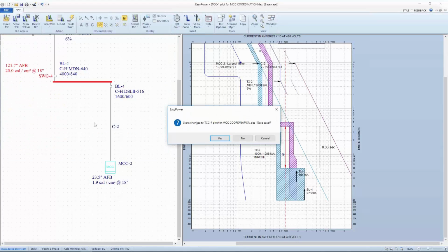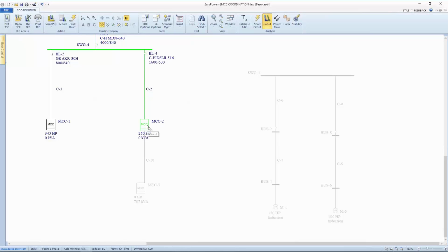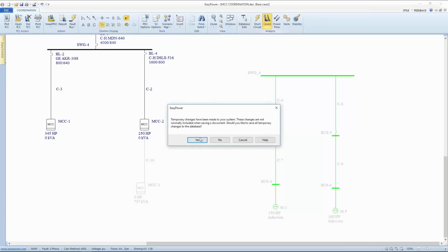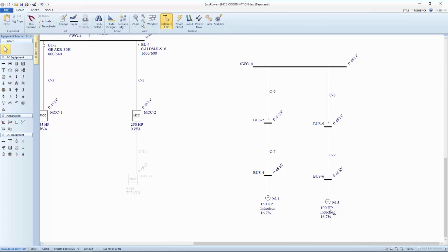So the question came up, what if I had a bunch of loads downstream, and in particular I could label the bucket that they're on as far as the MCC, but because these loads have within them, I need to go to my database edit. If this were my MCC bus and the downstream loads included large loads and lumped loads, how would I model it if I wanted to label disconnects that were downstream of the MCC? Well, the question is handled thusly.